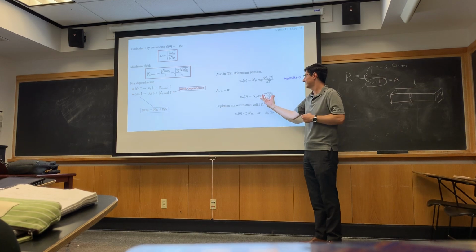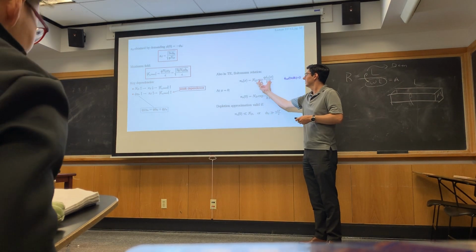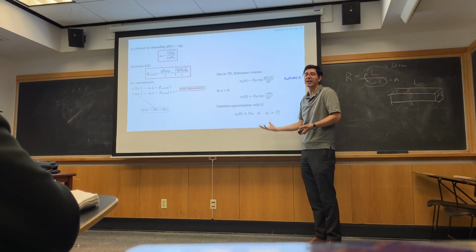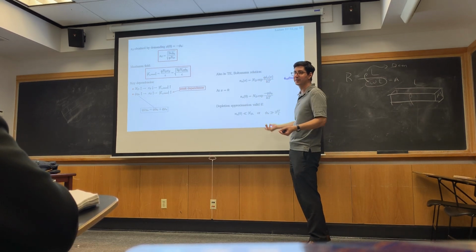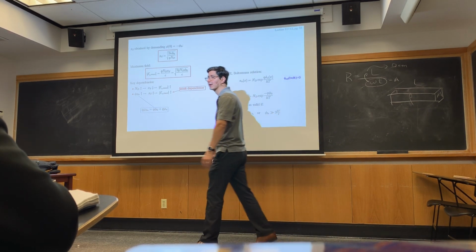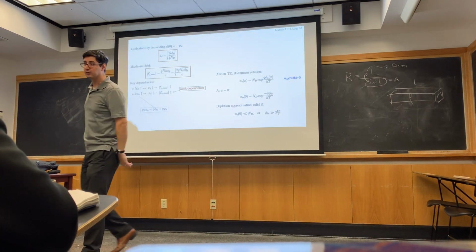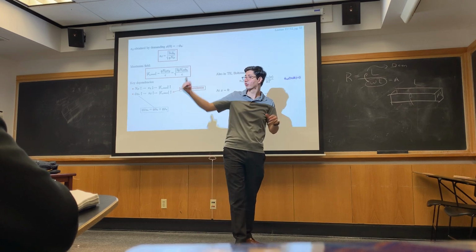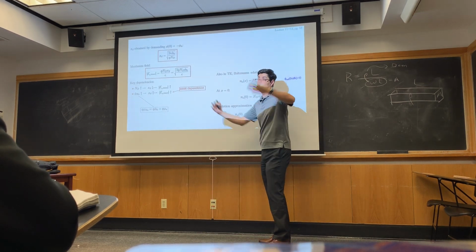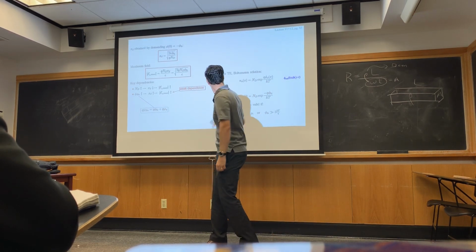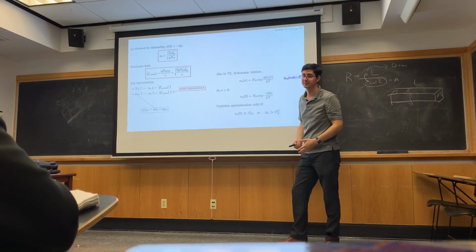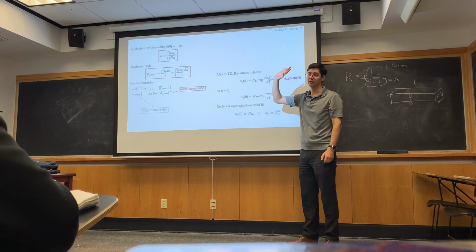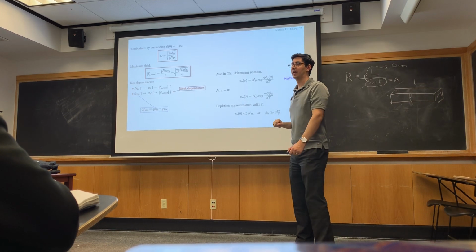This is the equation that gives me 60 millivolts per decade. It's all the equations of this form, exponential of something over kT. When kT is room temperature, that gives me 60 millivolts per decade. When the temperature is 150 Kelvin, half of room temperature, 300 Kelvin, then it's 30 millivolts per decade. That's just what this exponential gives me. And of course, all of this is assuming the Maxwell-Boltzmann relationship. What does that mean?